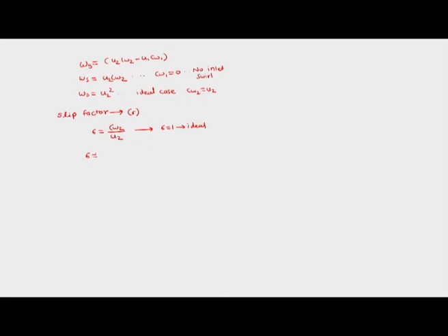However, there is a correlation which says that sigma is equal to 1 minus 0.63 pi divided by n for the non-ideal or real case, where n is equal to the number of vanes. We can see from here that as the number of vanes is increased, we will get a higher value of sigma.